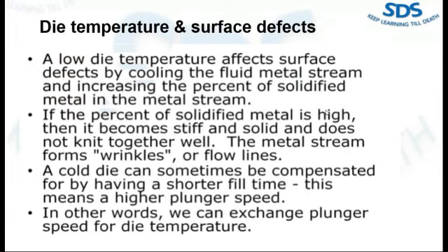So mostly on a shop floor, we are not able to maintain this close range. That's why we regularly adjust this high speed or spray time. Yes, because we are compensating for another factor. If we are getting low melting temperature, we can increase fill time by increasing plunger high speed. Please try to understand the combination of these parameters.